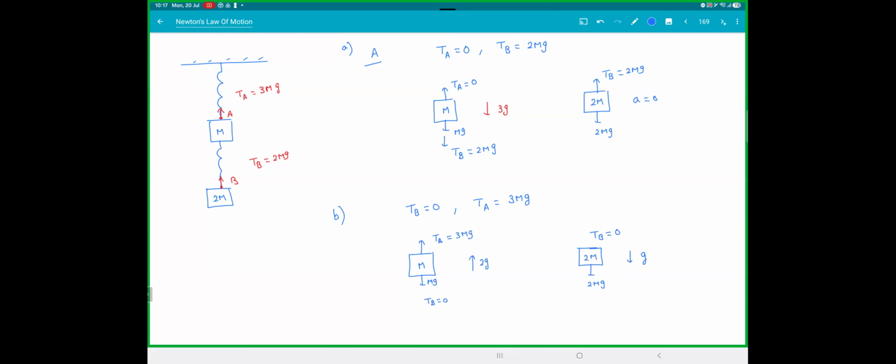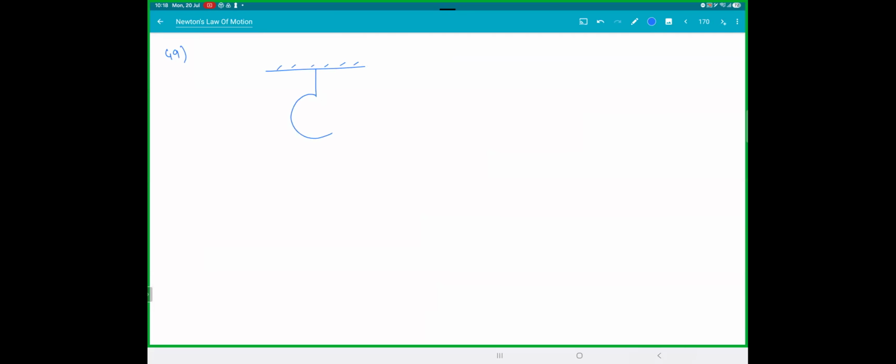Is that making sense, everyone? Clear? Easy. So find your initial tensions. Whichever you're cutting, make that 0 and everyone else will remain the same. And then draw a new FBD and finish it off. Let's see one more. So this is one set of problems, cutting off springs. They just cut it and they'll ask you.